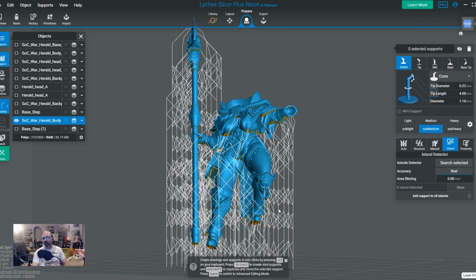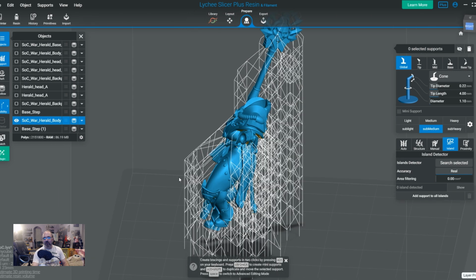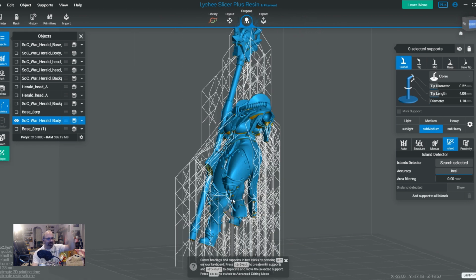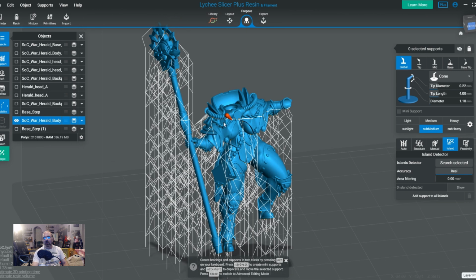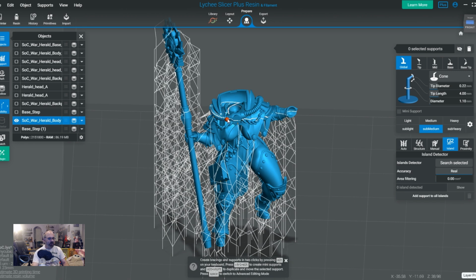One of the other things I can recommend to prevent failures is to always check your orientations. Make sure your orientations are conducive to a non-suction based print. If you've got hollows, please make sure the holes are facing down, where they're going to be able to drain an air vent. If you don't have hollows, make sure things that are going to create suction, you try to point at an angle, so that way the suction isn't completely forced, where it's just going to be popping on and off for this little hole, or anything else that's like a little pocket. That can create more strain on the print.